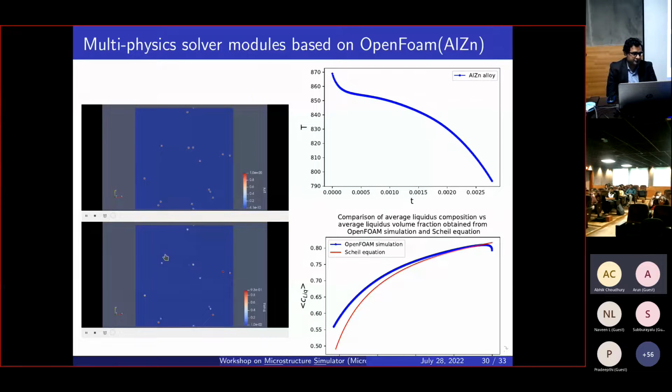So this is using the orientation field model. So this is not a multi-phase model, but this is an orientation field, as you will see over here. So this is the phase plot on the top, which is evolving. And at the bottom, the orientation field evolving. And as you are evolving, you are essentially cooling down. So your temperature is evolving. So you have cooling down, and then because of the growth, the temperature saturates because of the latent heat evolution, and then you start to cool again because the growth rate starts to drop. So you essentially have a typical cooling curve that is there in experiments, which can be seen over here. So I will let this progress a little bit.